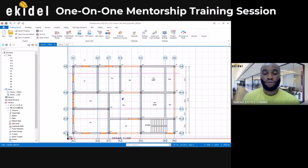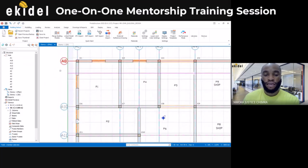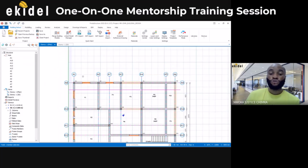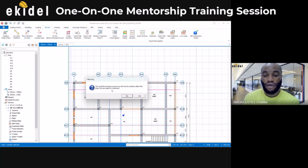Now, once you've done that, you can choose to rename all these axes so the vertical ones are 1, 2, 3, 4, 5, and the horizontal ones can be A, B, and C. To do that, I'll go to this tab here, the Review tab. Under the Review tab, I'll see Relabel Members. So I'll click on this, and then I'll say yes.